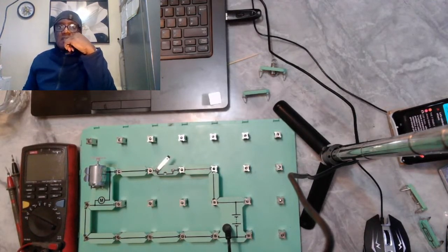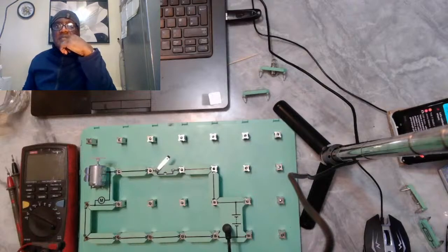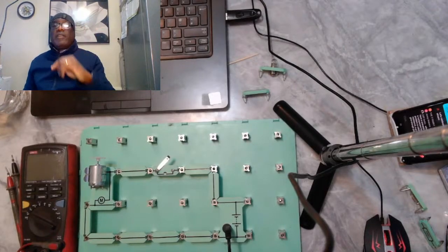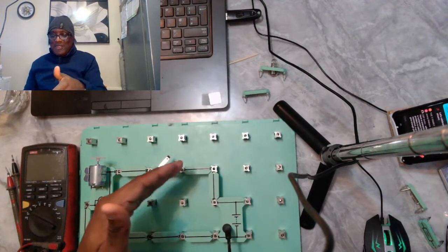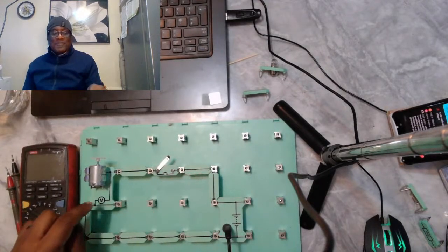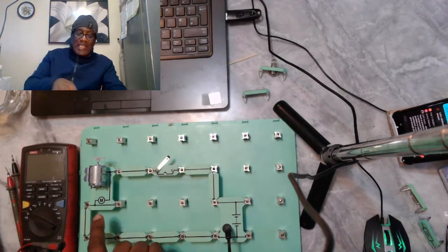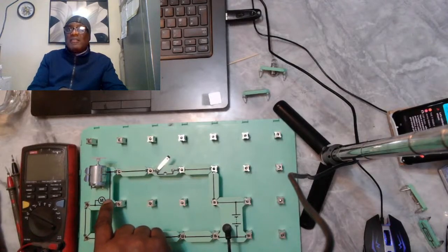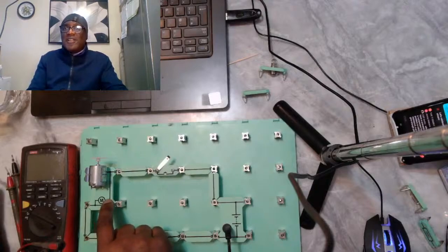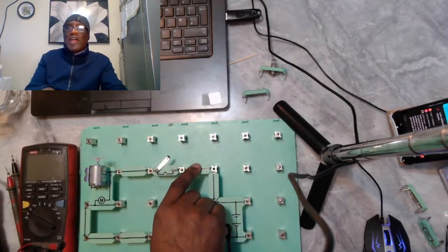Cliff has typed something, which means we might have a scenario whereby we condemn a component for not working while the problem is within the wire. Correct. Yeah, Cliff is right. He's saying that because of the high resistance we had here, sometimes we miss it and then come and condemn the load itself, when the issue is in the wiring.